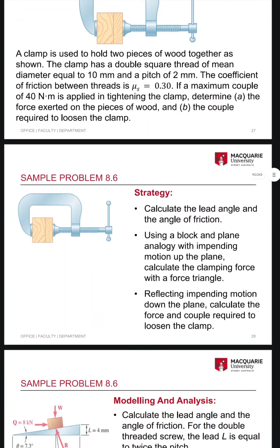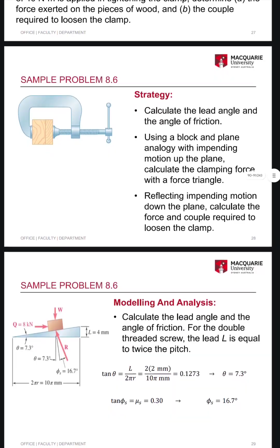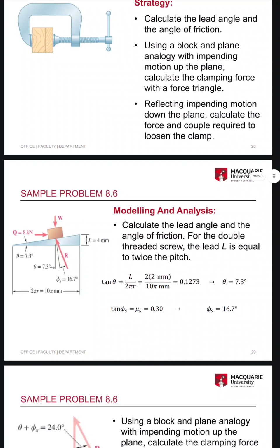Strategy. Calculate the lead angle and the angle of friction using a block and plane analogy with impending motion of the plane. Calculate the clamping force with a force triangle reflecting impending motion up the plane. Calculate the force and couple required to loosen the clamp.